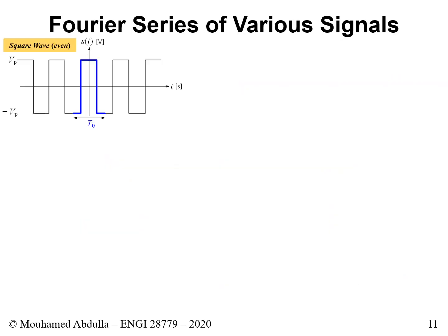Finally, we arrived to the last slide that I'd like to show you in this lecture, which is the Fourier series expansion in the time domain for the various signals. And of course, when you have the Fourier series expansion in the time domain, you could right away jump into the frequency domain, irrespective of the sinusoidal. If it's sine or cosine, it will be the same thing. Does not matter. You simply look at which harmonic it happened, and then you just put a spike in the frequency domain. And we showed this in lecture 3, but this also applies here throughout this lecture.